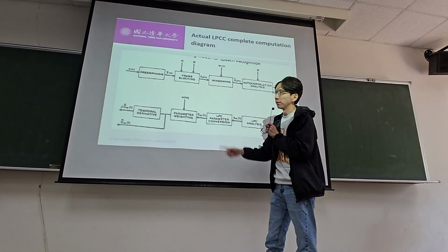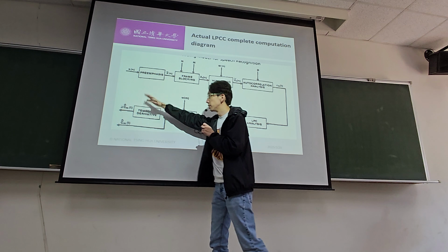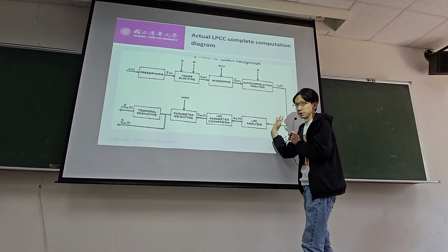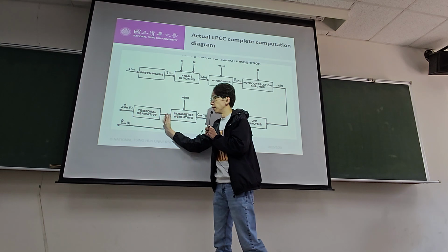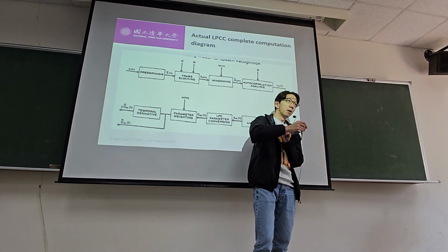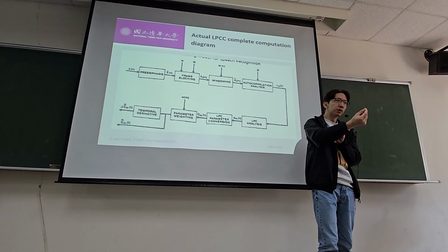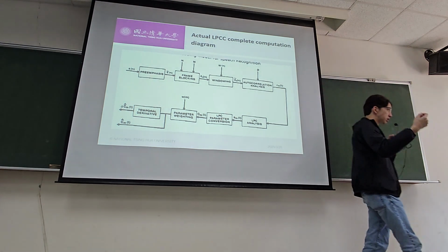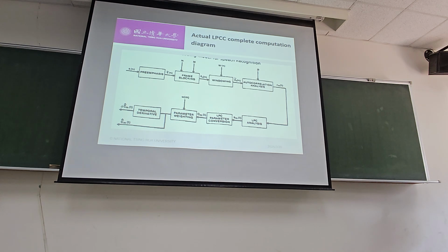But this overall framing you can keep in mind, okay, so from the speech signal, through some short time, through some spectrum representation, then eventually add a bit of temporal information to represent that particular frame, then move on to the next frame, repeat this process, move on to the next frame, repeat this process, so that you can start deriving all these features.